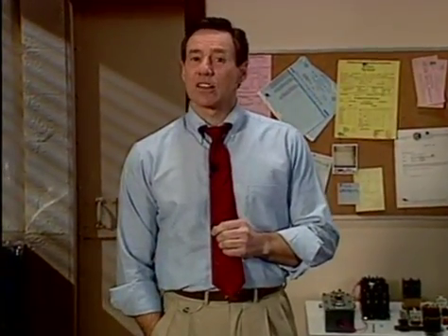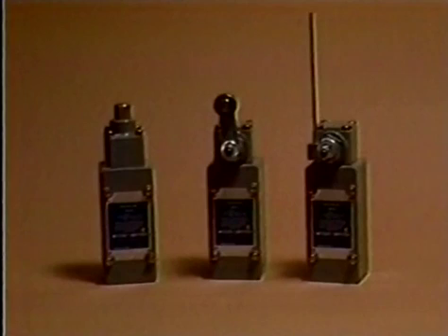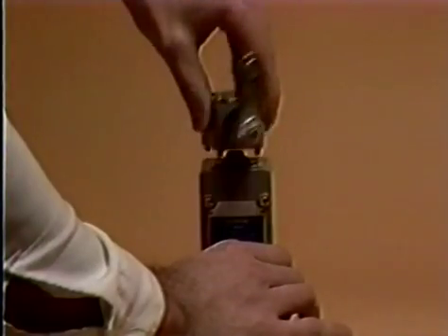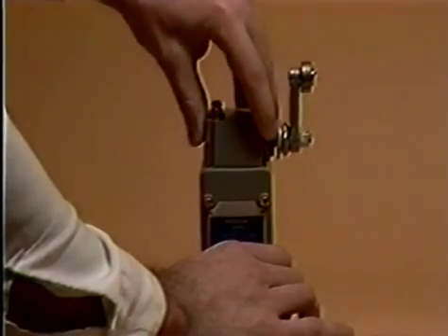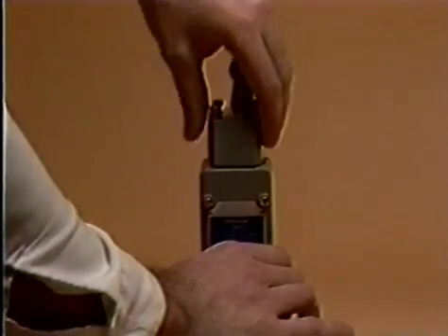As an electrician or technician, you will be required to install, troubleshoot, and select limit switches in your plant. This will require you to be able to select the best actuator for the application and mount the limit switch in a correct position so that the moving part hits the switch actuator in the right place and that the manufacturer's specifications on hand are followed.